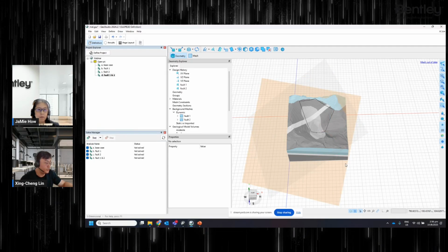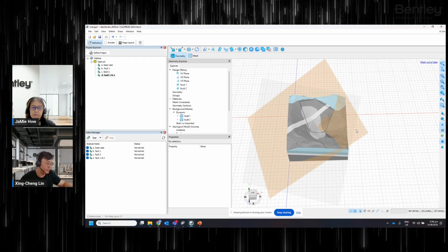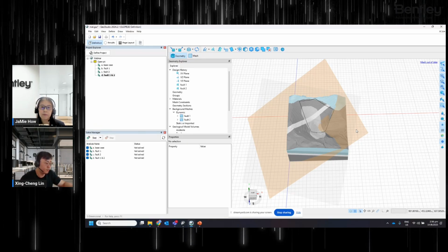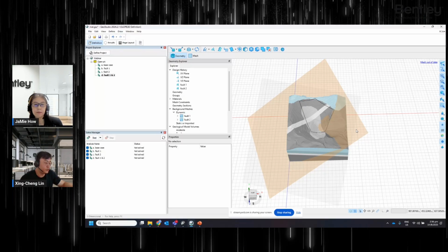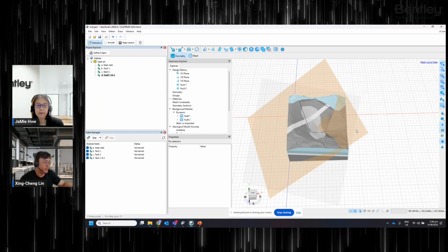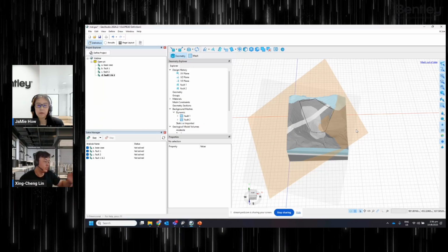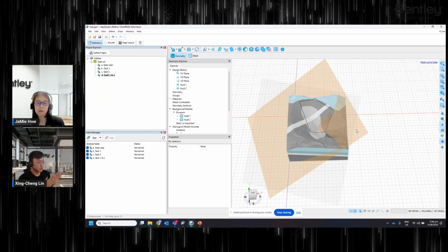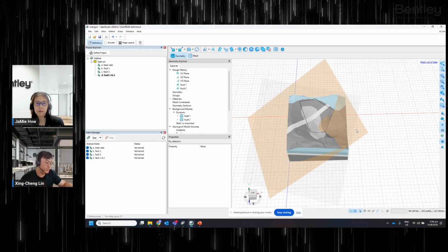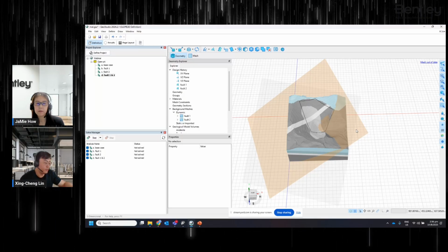About the weak surfaces, some of you might have the question, what's going to happen when the slip surfaces get introduced into the geological models? This is how it works. If it intersects fault number one, the ellipsoid will actually be truncated, and you will therefore follow the weak layers. And then whenever it intersects with the ellipsoid again, it will re-emerge near the toe. So this is how the stability is being structurally controlled. We'll see that more clearly when we go to the results.